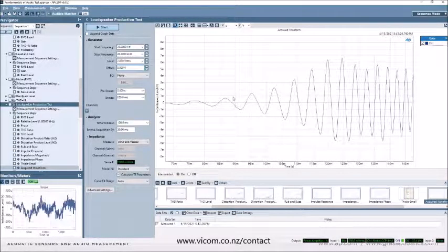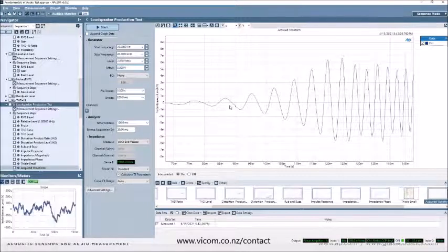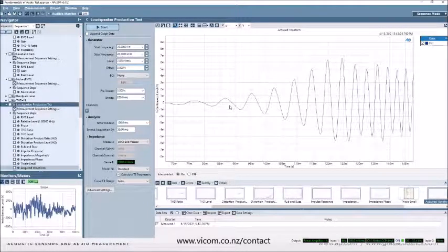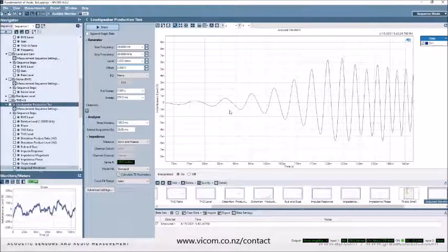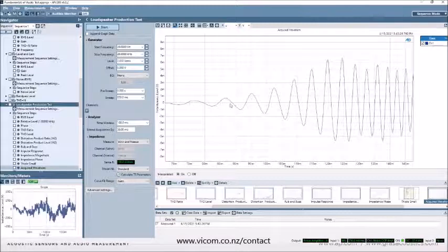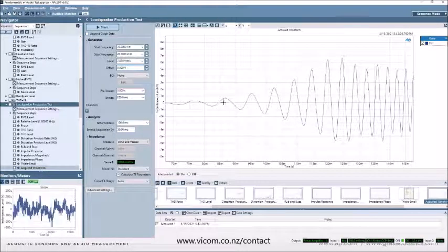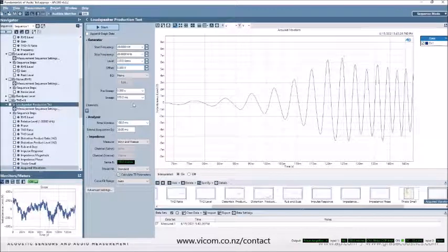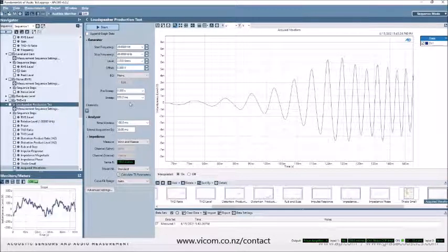In the different types of sweeps, such as a classic step frequency sweep, the signal generator would actually dwell at each step, each fixed frequency, for a period of time. It would be no different than if we generated a standing signal and manually incremented the frequency.